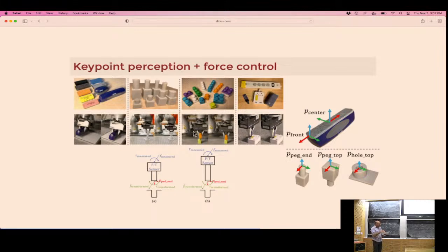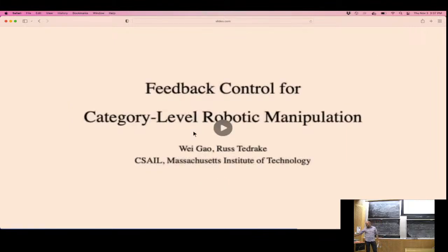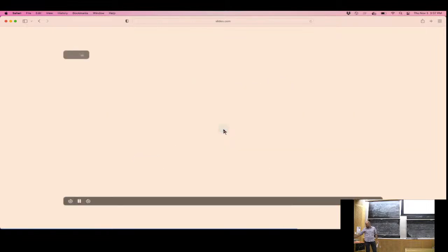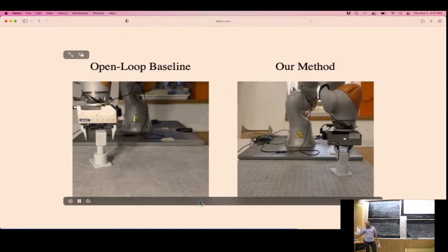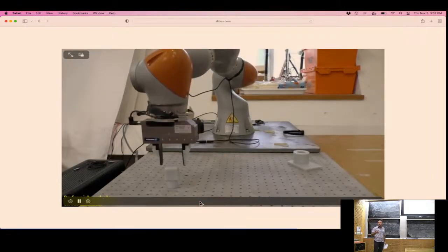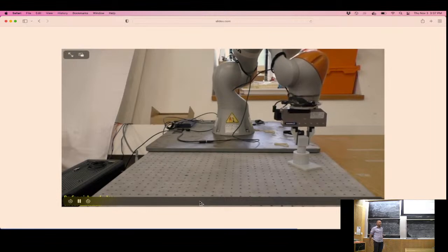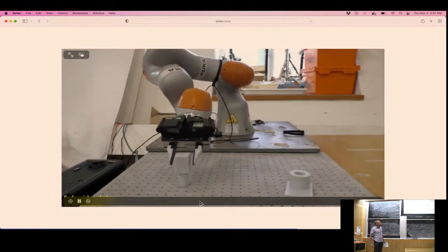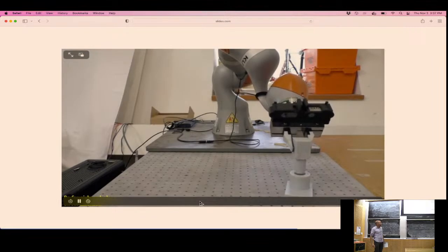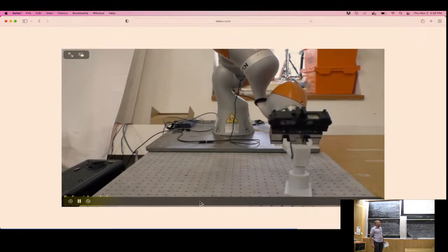And then if I assume the object is fixed to the hand, I just have a slightly different end effector on my robot. I have a Jacobian that's just slightly different, but based on the location that came out of the key point estimator, and I can suddenly apply impedance or stiffness control at the end effector of the tool, right? And that's what made the examples I showed of erasing and plugging in and things like this. This was impedance control plus key points. I think there's probably lots of potent combinations of the different tools, but you do need to know where the location of the contact is in order to get that done.